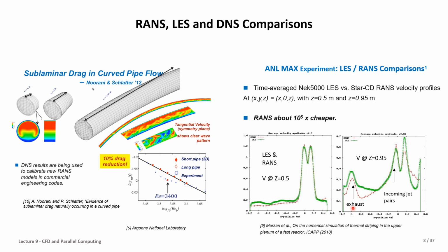Also in this report, there was a point that when they changed some element in the geometry, RANS could not capture this detail and presented a similar result to before the change in the geometry. However, LES presented the change. That means in some problems, RANS could not provide the detail and we have to apply LES.